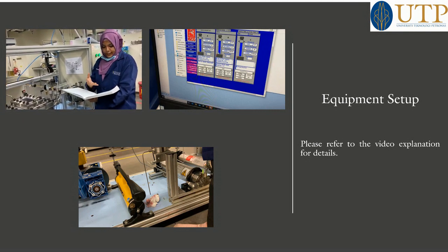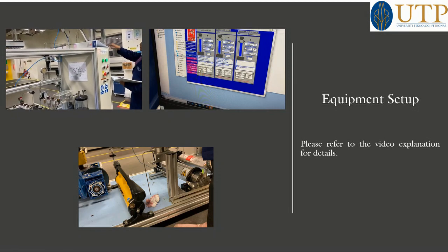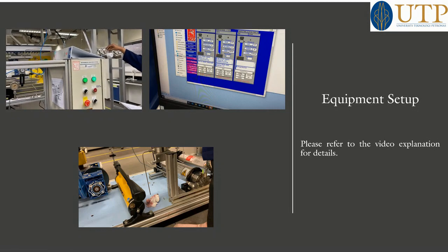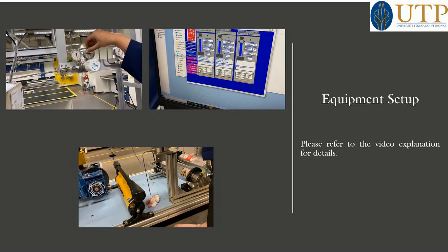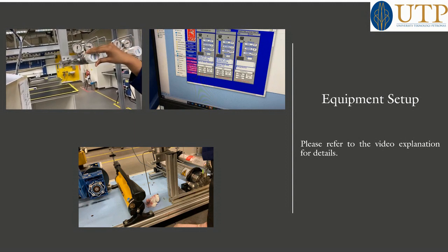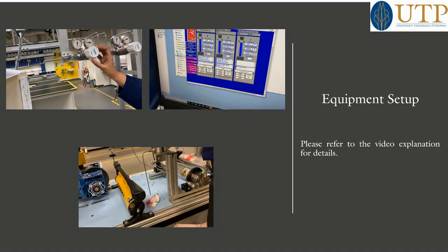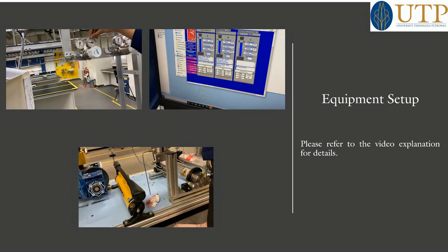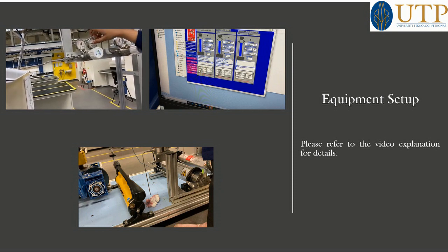So now carbon dioxide pressure increase. So here we can see they already supplied 700 psi from the cylinder. So now how much I want for my experiment, I will set it now. So the first thing, if you want 2000 psi, then you have to set the cylinder till 2000.